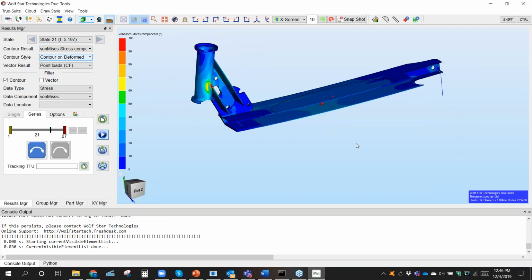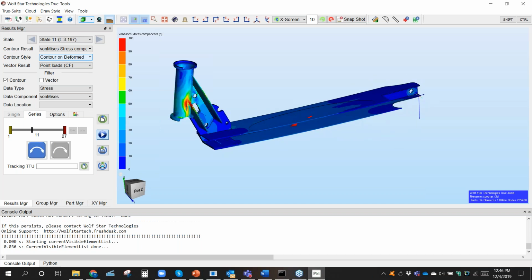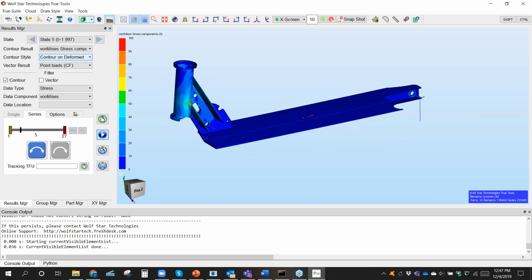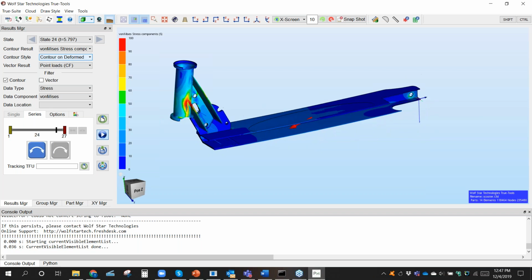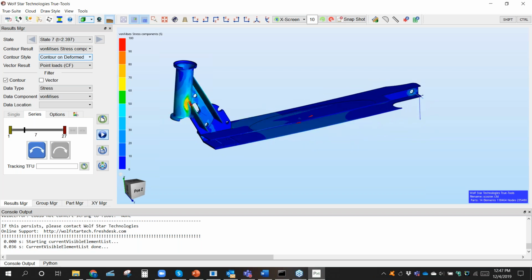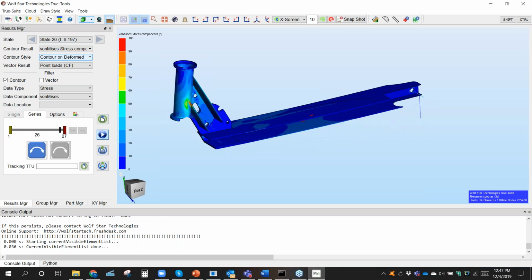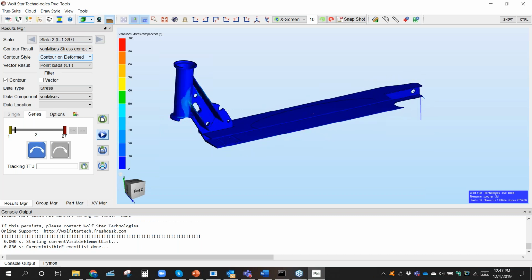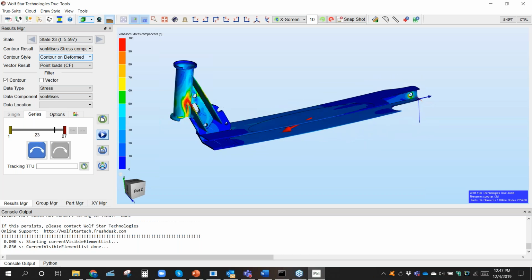All right. So now that you've got these types of loads, you can go off and use tools like FE Safe to do fatigue analysis on this, and you can really drive and optimize your design. So this is all about understanding the loading on your product, and you can see how in a matter of 20 minutes here, I was able to go from beginning to end to get the loads in this thing.